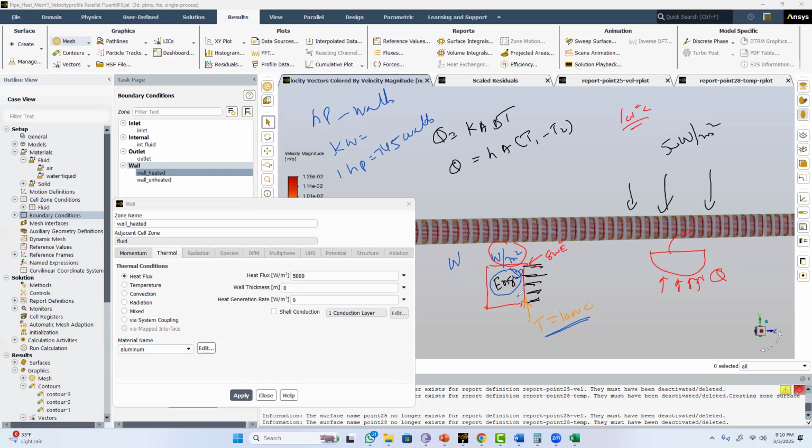If it is not efficient, temperature may go up to like 1500 degrees Celsius. So this constant temperature is one of the equilibrium conditions that is being applied there. But the heat flux here is a design value, from some mechanism, some device. We have some heater, and that heater will produce some energy in watts. If we divide that energy by the area of the equipment, we get the heat flux, watt per meter square.